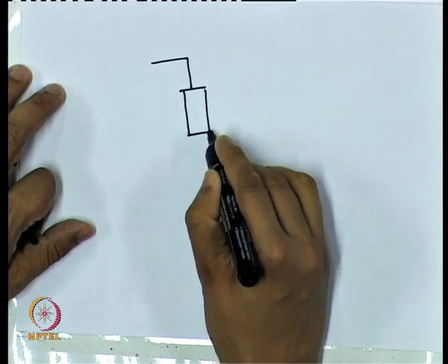So, to understand the way in which we can do this, let us see again an example. So, we already saw that when we have an inductor in series or shunt, we can shift our impedance or admittance, and they will be shifted upwards in a ZY Smith chart. When we have a capacitor in series or shunt, the impedance or admittance will be shifted downwards in a ZY Smith chart. Therefore, let us consider that we have an impedance.